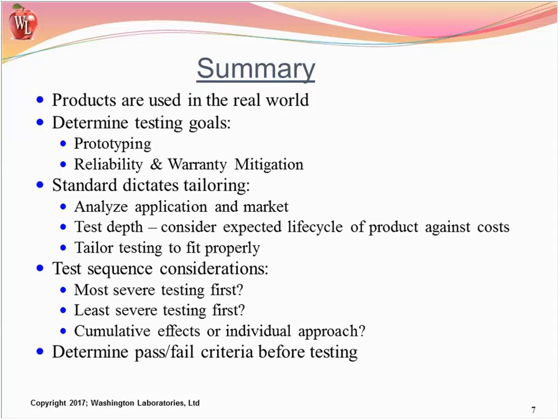If you go out and buy a $1,500 drone, your expectation is that while the warranty may be very good, you really don't want to have to use it. And that's where testing can help significantly. You can look at HALT testing, which is highly accelerated lifetime testing, which gives you a very condensed, high-level test to give you an idea and an expectation of how long the products are going to last. It's not always bomb-proof, but it does work pretty well.